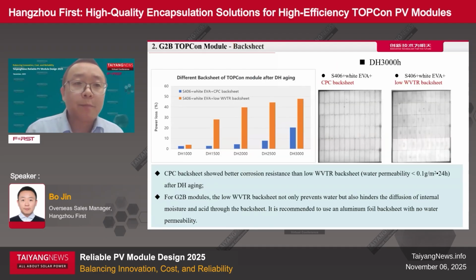So for the glass backsheet TOPCon, the backsheet is also one factor for reliability. And we also tested and compared the standard backsheet and the low WVTR backsheet. We used anti-acid EVA on the front side and white EVA on the back side for this comparison test.